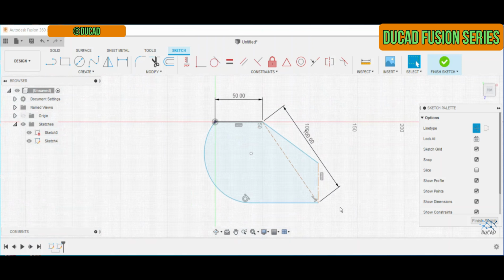And if you want to turn this center line into a line, then select it and then select this option. It will turn into a line, and you will notice that the whole sketch is selected as an entire sketch entity. It is not split as we saw previously.